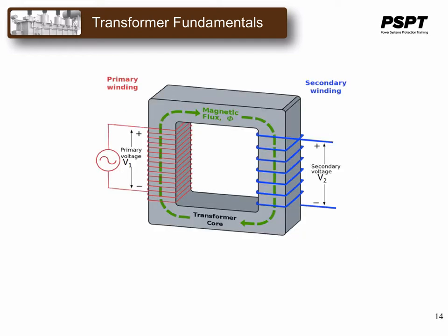If we wind two coils on a steel core, we can cause almost all of the flux to be linked by both coils. And we can further hypothesize the case in which 100% of the flux is linked. In this case, it is called an ideal transformer. In coil 1, the flux produced by the generator is related to the voltage by Faraday's law.